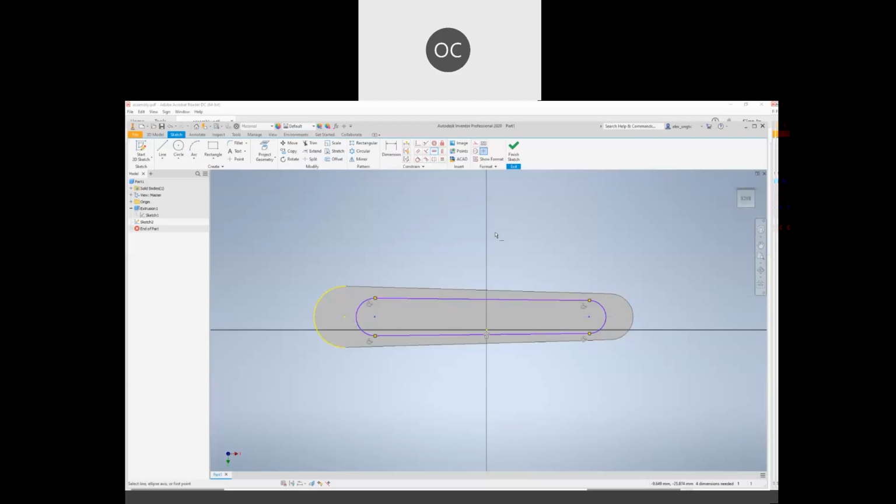Okay, after that, you should also ensure that it is vertically constrained. So vertical constraint, try to look for the midpoint. The midpoint of this top line here and the midpoint of the primary feature. So you will see here midpoint. Please look at the midpoint and then the midpoint. So they should be aligned. Okay, like this. They should be aligned in a vertical sense.